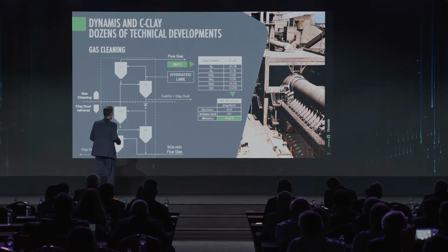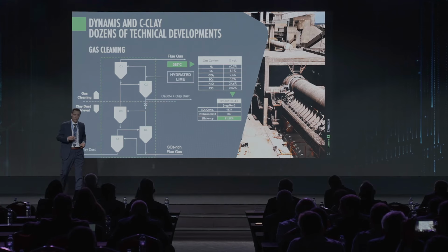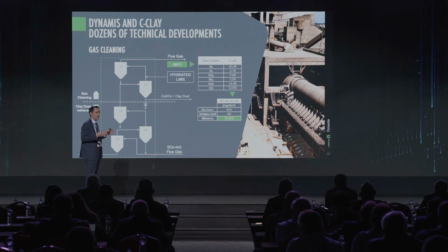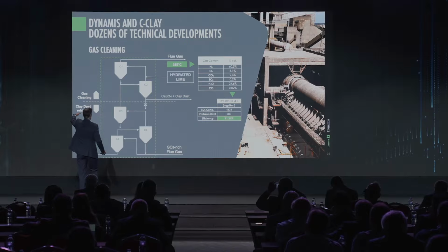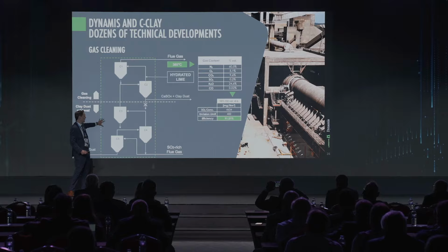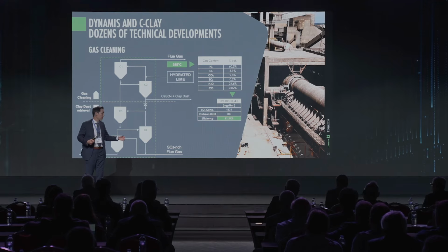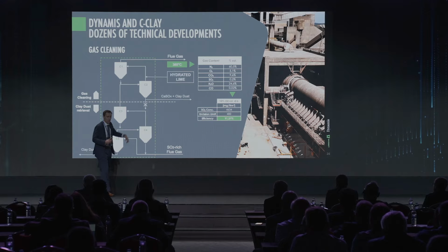And now we are proposing this, that is to modify the preheaters of existing clinker kilns to work as a dry scrubber. The idea is to divide the preheater in two parts: the bottom part to collect the dust and recirculate this dust, which is normally a very good clay, and the top part to inject hydrated lime and clean the flue gases.